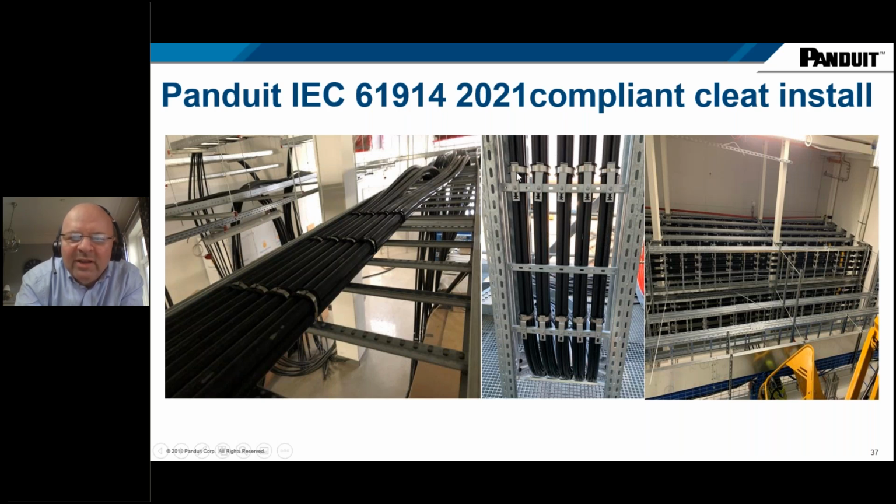It's also worth noting that you do not need to install a bracket on every single rung. You can install it on alternate rungs and use a stainless steel cable tie to hold this cable in this position as well. Finally, you can see here the bundle forming a quadrifoil formation. And this cable tie can be used around single cables, trefoil cables, and quadrifoils. And remember the benefit: half the cost, half the installation time, half the application space here, and half the storage space.